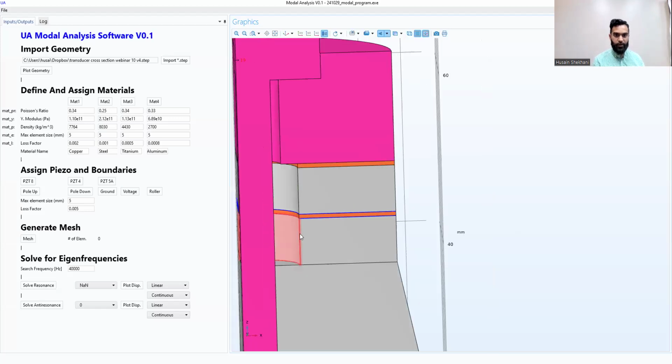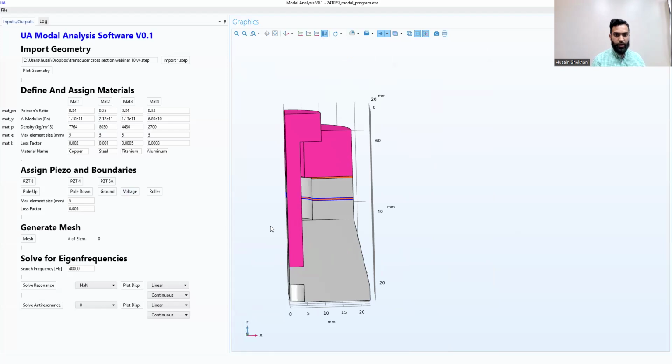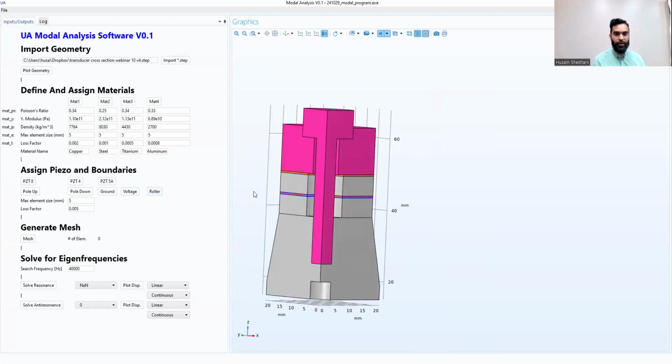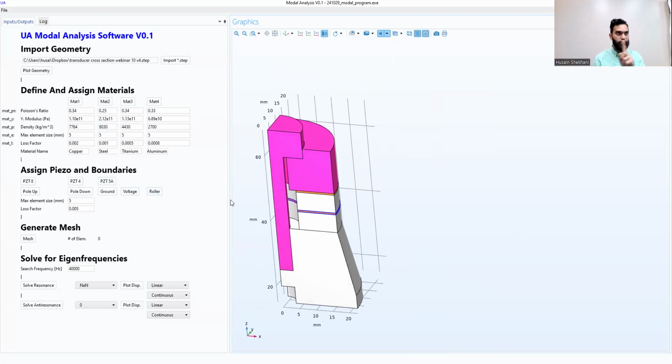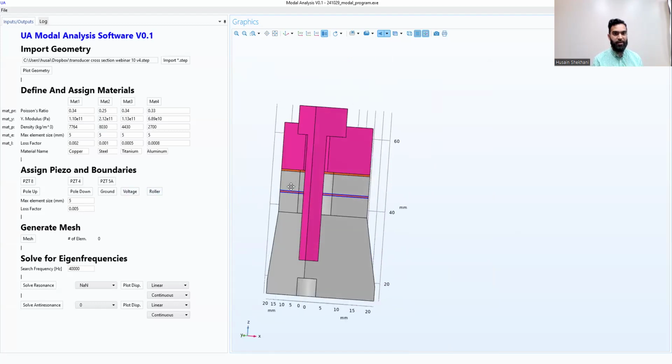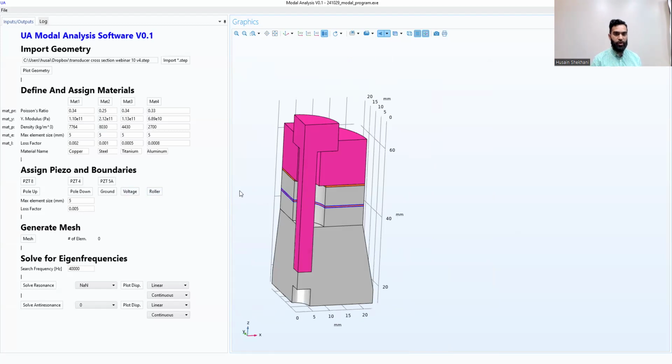The next thing I want to talk about is the roller boundary condition. You can actually import a three-dimensional, fully revolved geometry. I didn't do that because if you do a quarter geometry, or even more narrow, like a pizza slice, depending on how many slices you take, you will use less and less mesh count. So if you want it more detailed, you'd probably want to use more symmetry, a smaller geometry via symmetry and boundary conditions.